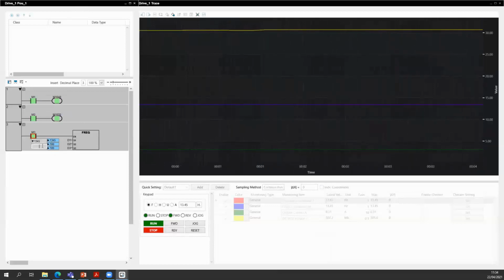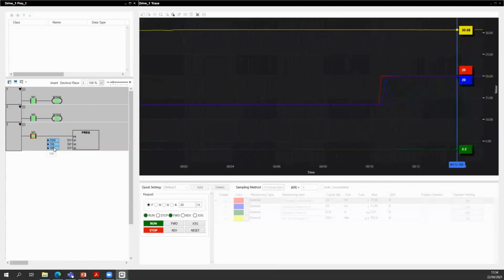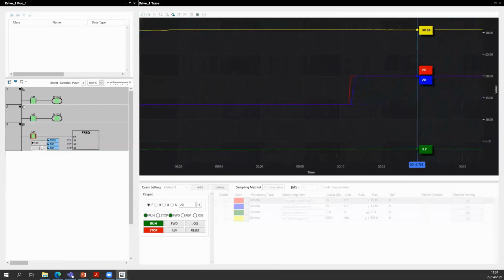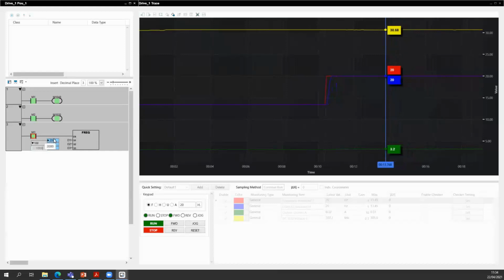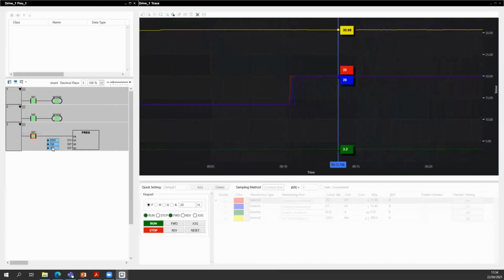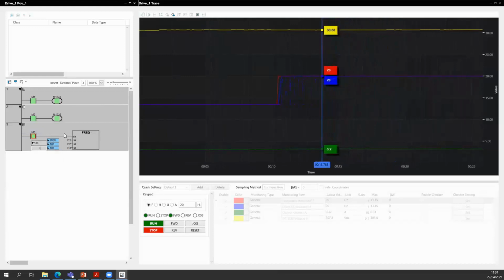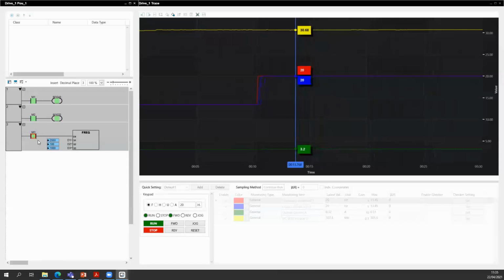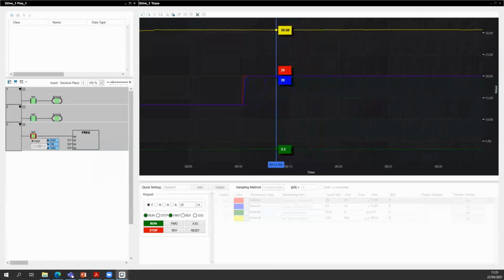I can change this to 20 hertz. So I set here 2000, and then you can see it here. I can change the deceleration ramp to be much slower, so I can set it to 10. Yeah. So now it's okay. Can give it a frequency command of 10 hertz.